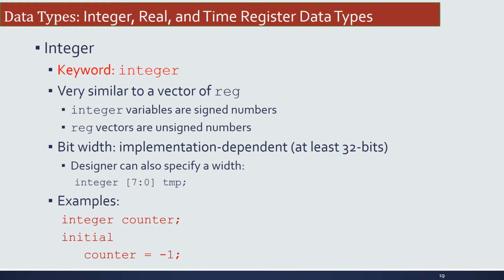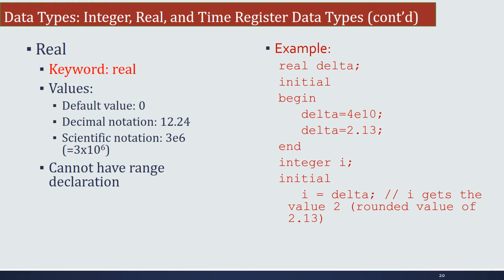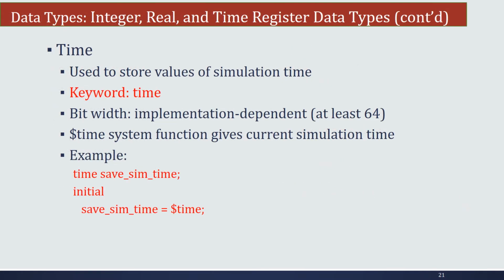And another type is integer. You have a provision to represent any value with a signed integer. Here it is a keyword, maybe used in behavioral programming. Similar to integer, you have the keyword real, used to represent some values in variables. Time is another keyword, where whenever you want to track the timing, time is a keyword directly used, so that the timing of the simulator can be transferred to this variable.